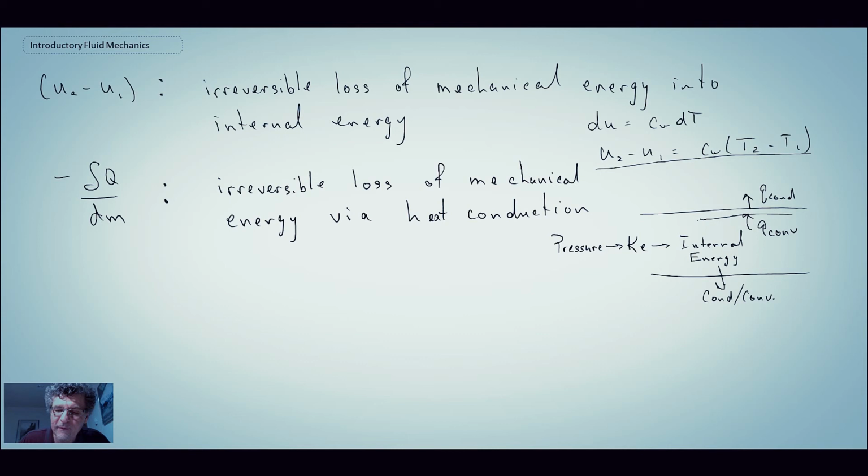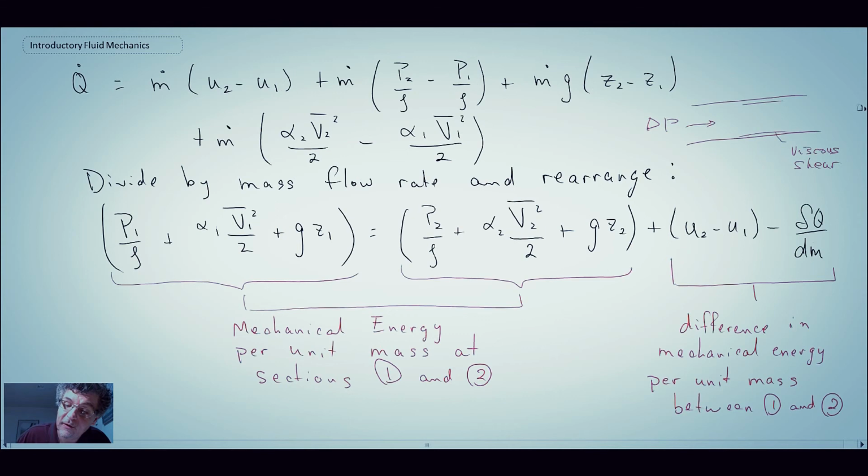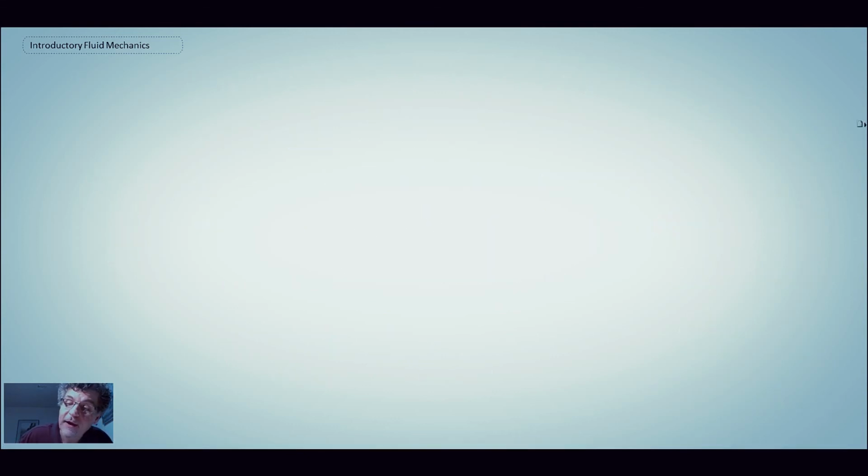If you have a turbulent flow, it would be a higher loss mechanism, and there are a lot of theories about that, because all turbulent energy goes from kinetic and eventually goes to the inner scale, and then into viscous shear. We won't be getting into a lot of that in this course. What we're going to do is take these last two terms and encapsulate them into a loss term, which we'll call a head loss term, and that's how we handle this loss mechanism.